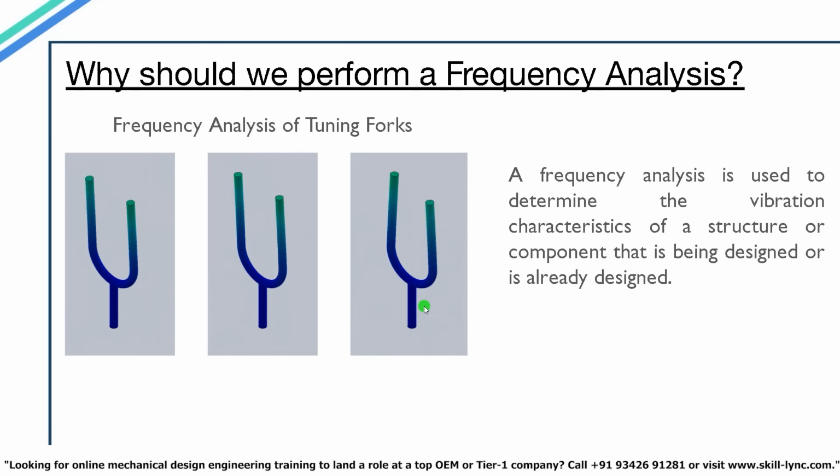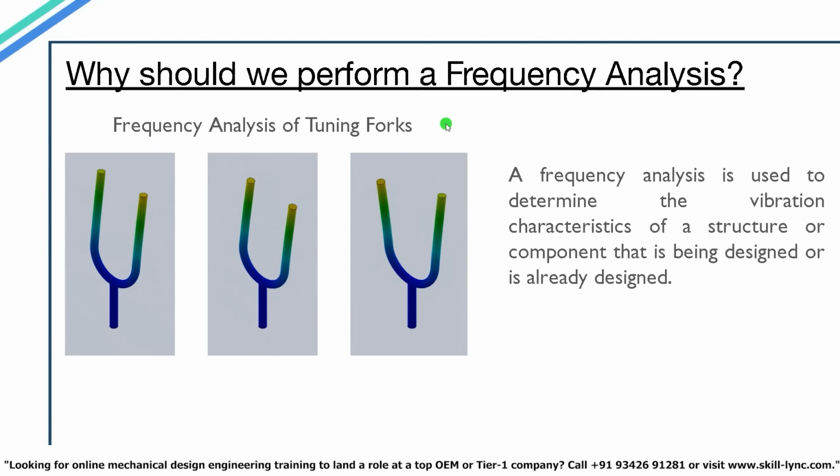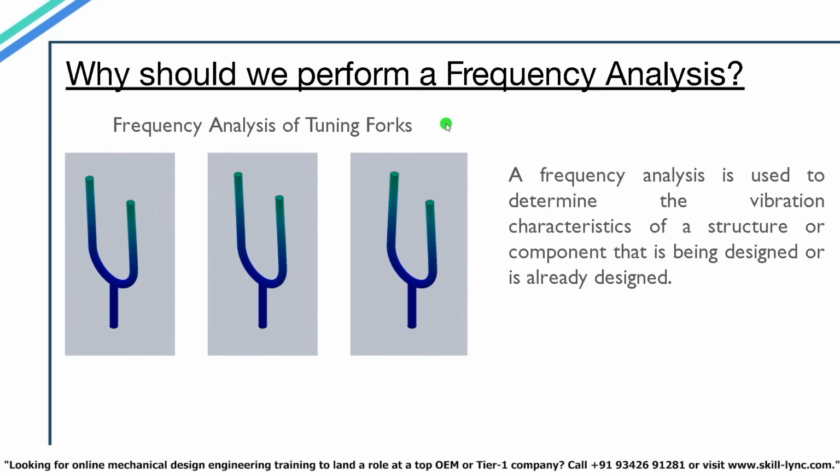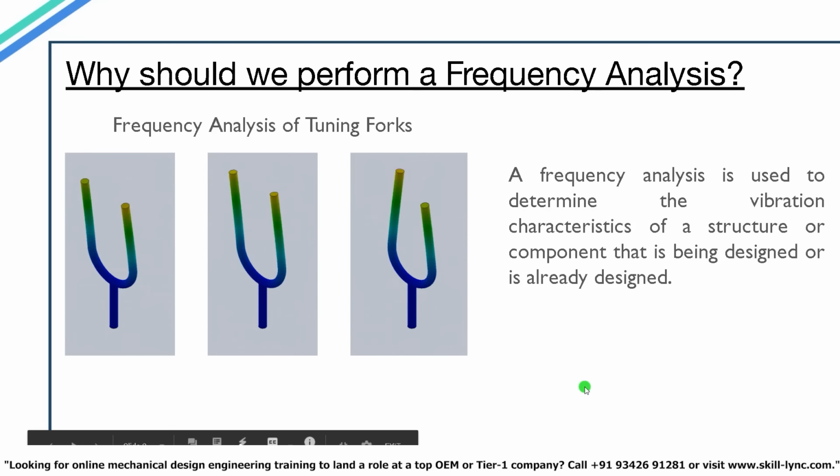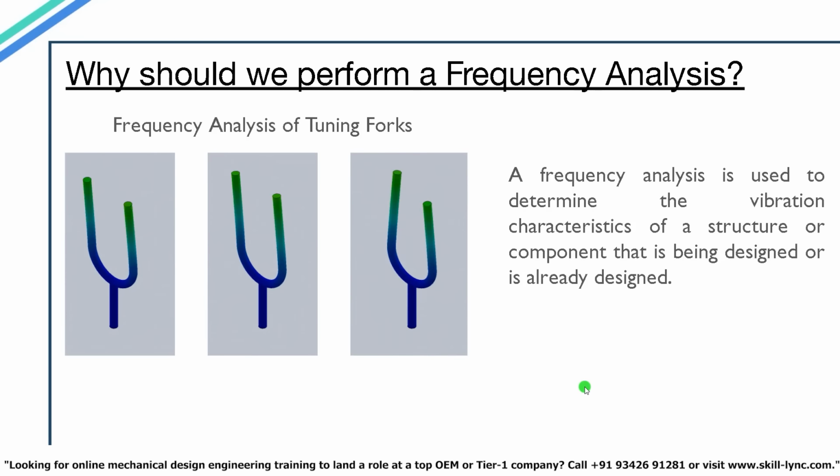The first question that we will be asking ourselves is, why should we perform a frequency analysis? A frequency analysis is used to determine the vibration characteristics of a structure or component that is being designed or is already designed. So why is it important for us to know how an object vibrates or at what frequency it vibrates? To understand this, we need to have knowledge of 2 topics. The first one is natural frequency and the second one is resonance.